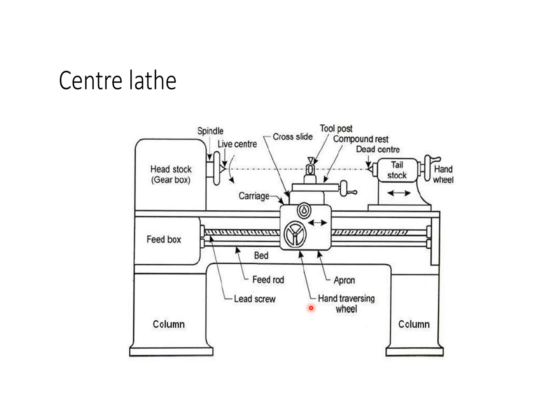Next, lead screw. The lead screw is a long threaded shaft used as a master screw and brought into operation only when threads have to be cut. At all other times, the lead screw is disengaged from the gearbox and remains stationary. The rotation of the lead screw is used to traverse the tool along the work to produce screw. The half nut makes the carriage engage or disengage the lead screw.